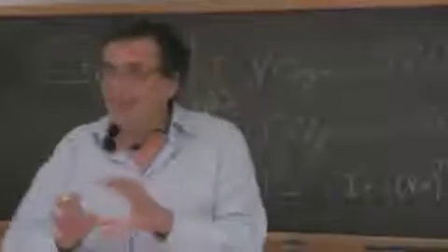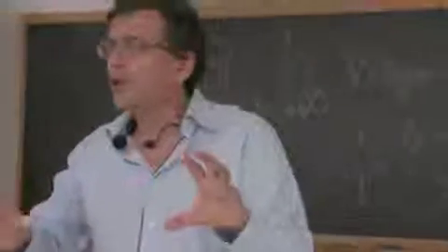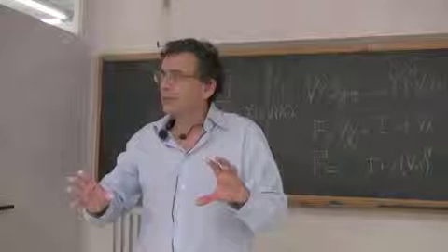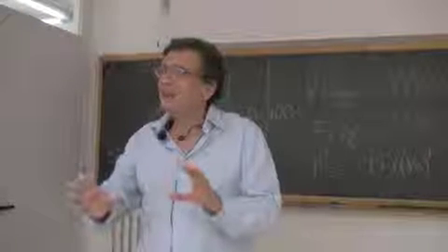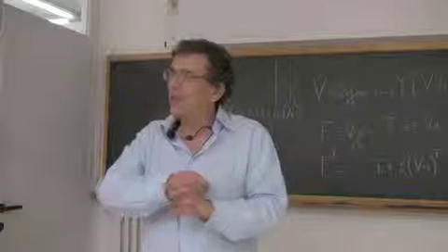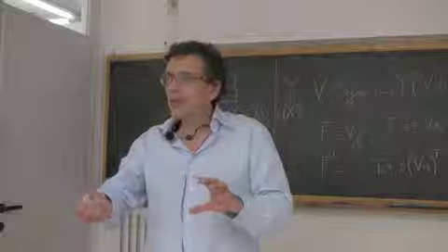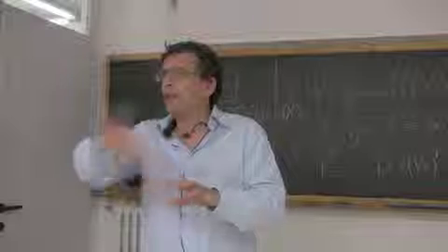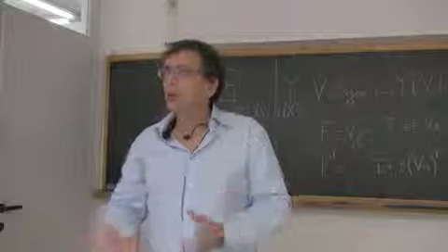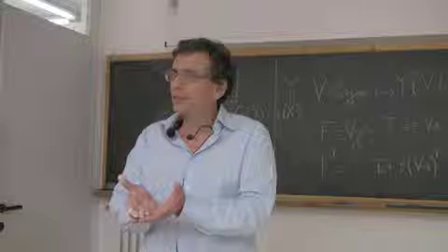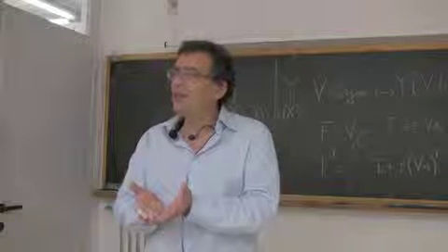So, what will we do next? We take the general constitutive equation for isotropic solids and we linearize it. So we develop it in terms of Taylor series and we kill everything which is epsilon square, epsilon cube and so on. And we remain only with the linear part. What will we discover?